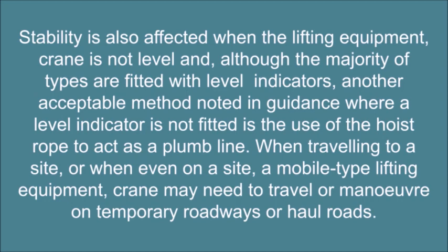Stability is also affected when the lifting equipment crane is not level and, although the majority of types are fitted with level indicators, another acceptable method noted in guidance where a level indicator is not fitted is the use of the hoist rope to act as a plumb line.